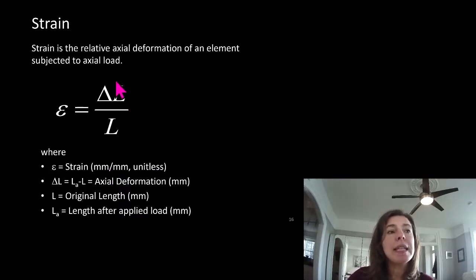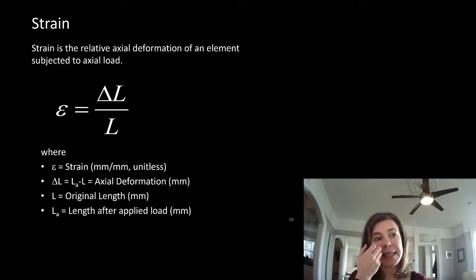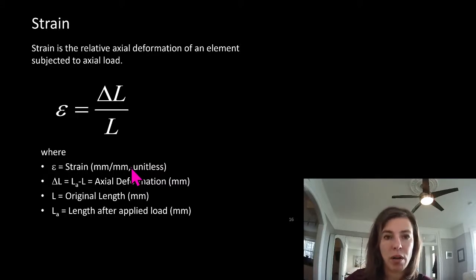Well, we're going to see a relationship between strain and stress that allows us to basically expand these equations a little bit. So I'm going to strongly recommend that when we're doing calculations to convert it to millimeters, just so that we're consistent. I find it handy too, sometimes, to always write millimeters per millimeters, just so that I remember what's going on with my strain.